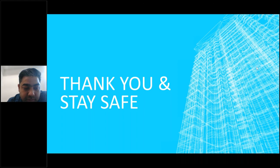So what usually is done again depends on top management's drive to push and create a culture of looking for these things, where windows or any openable areas like doors need to be shut. And in back of house areas within, let's say, a hotel or a mall, where there is a regular chance of the door opening, we propose to install air curtains so that the loss can be reduced. So even when the door is open, at least the air curtain is blowing and limiting the conditioned air from going out of that particular zone. So that is one way of doing it.